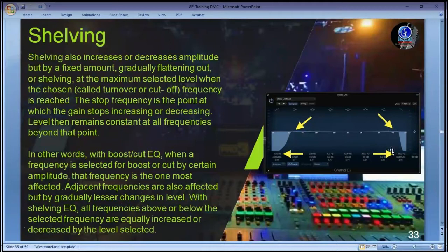Now, what I just explained before: if you want to cut down on 1K and you select 1K around here, see where my mouse is, by the time you draw your 1K down, it will also draw down a bit of 3K, and from 3K to 2K, or 2K and 3K, 4K. So it means that the particular frequency you are working upon, some other frequencies that are very close to it will also be worked upon. So it will give you a range. But the particular one you selected will be where the emphasis is, where the point is. That's what is being explained to us here.